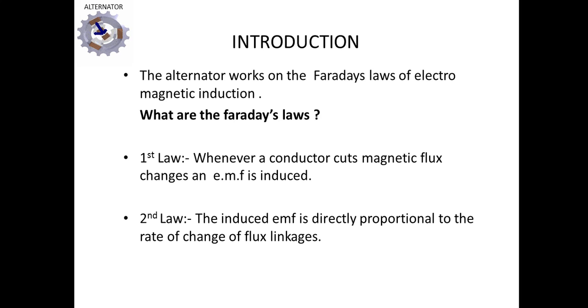The first law is used for motors and generators, DC as well as AC. So for the AC and DC generator we use the first law: whenever the conductor cuts the magnetic field, the EMF is induced, for DC machines as well as AC machines. The second law of Faraday's law is used for transformers, where there is a rate of change of flux. To induce the EMF, we need three things: the conductor, the rotating magnetic field, and relative motion.